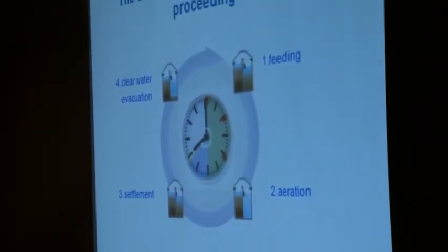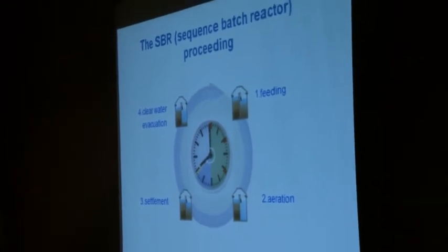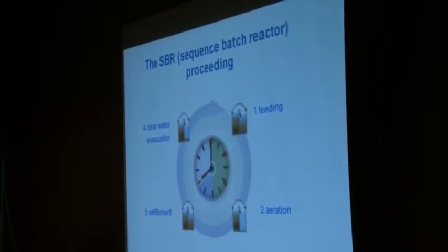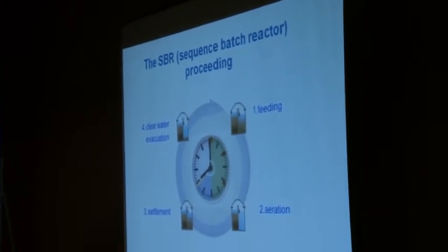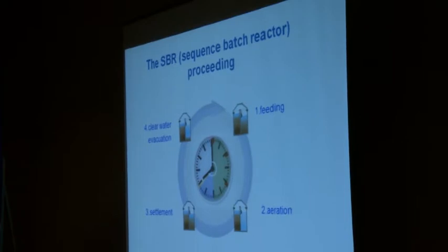The SBR process which had been used here is a SBR process which lasts at least about 8 hours. That means the water will be treated in 3 cycles a day. The difference between the traditional systems and an SBR system is that all parts of the treatment will run one after another. So the different steps of treatment are separated by time and not separated by the location in different tanks. That has also the big advantage that you need less footprint for such a system.